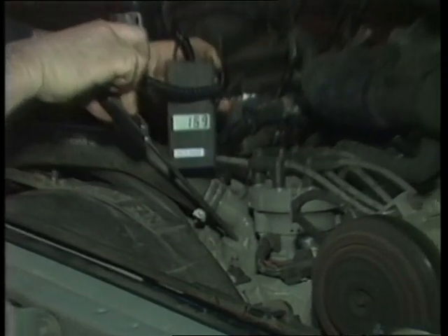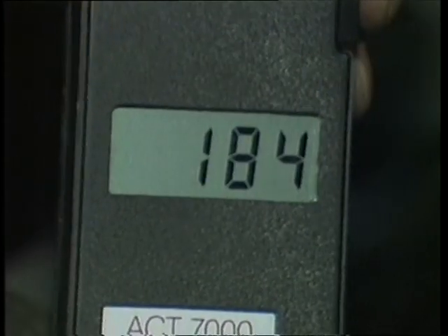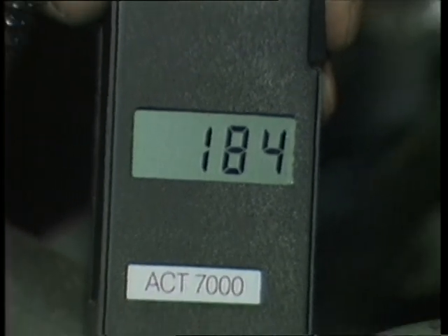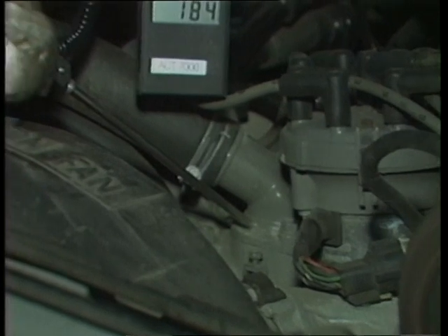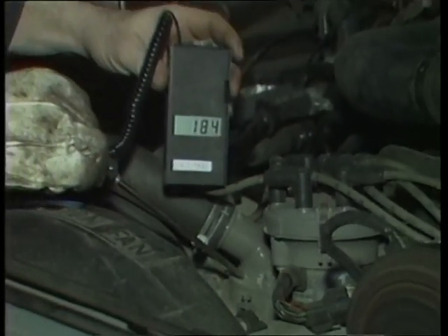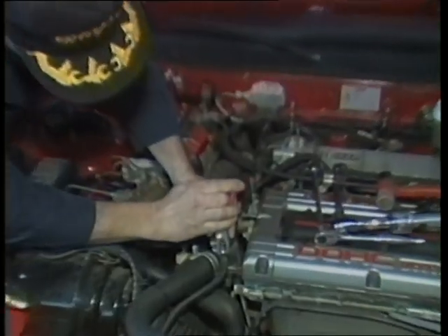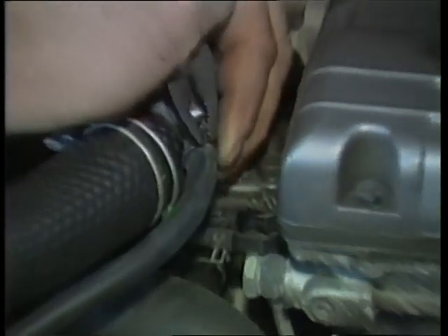To quickly check the operating temperature of an engine, use a digital pyrometer. Touch the probe on the thermostat housing right next to the thermostat, then read your digital pyrometer. If engine operating temperature is too low or too high, you have found a problem with a thermostat, radiator, fan clutch, or other part. To remove a thermostat, first disconnect any hoses going to the thermostat housing.